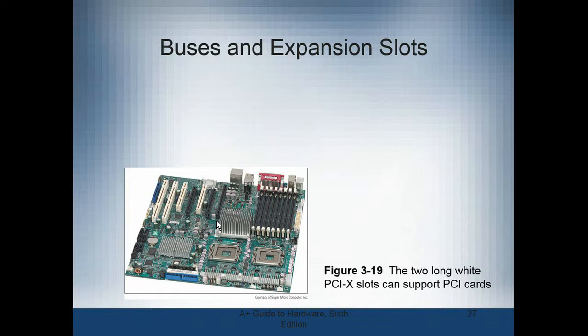One of the things that you may run into if your machine starts acting erratically, and we have a number of older computers around here where the capacitors just kind of explode. The capacitors are on here to maintain a steady voltage. And as they start popping, and you can tell because they get oil all over them, you may want to look at, going to have to replace this motherboard pretty soon because they become erratic.